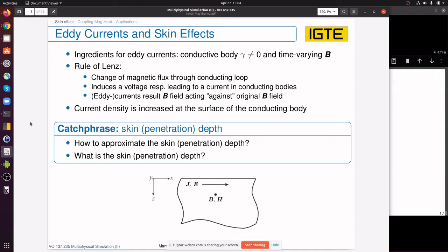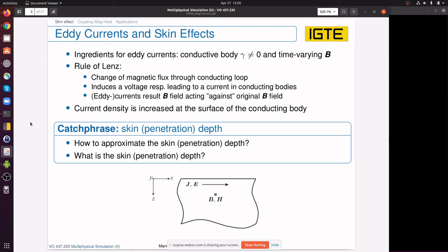It is crucial that you perform an approximate calculation of how deep your eddy currents, or Joule losses, will penetrate the material, so that for thin sheets the eddy currents don't cancel each other out.